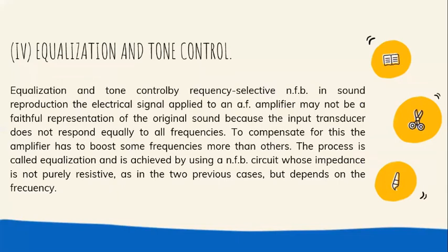Equalization and tone control. Equalization and tone control by frequency selective NFB in sound reproduction. The electrical signal applied to an AF amplifier may not be a faithful representation of the original sound because the input transducer does not respond equally